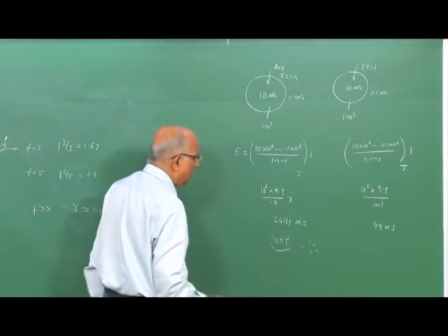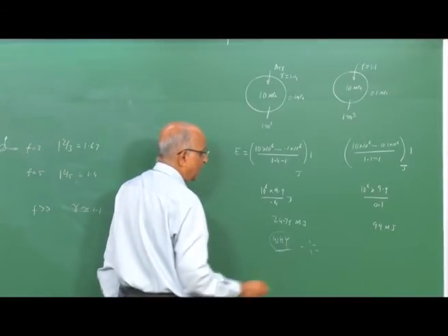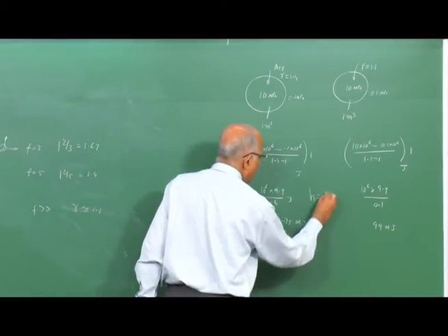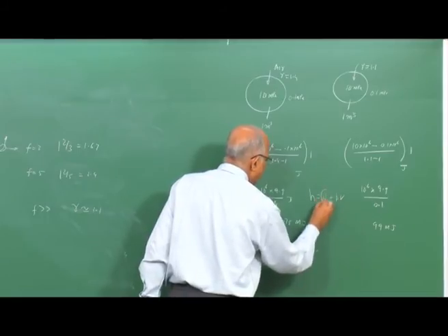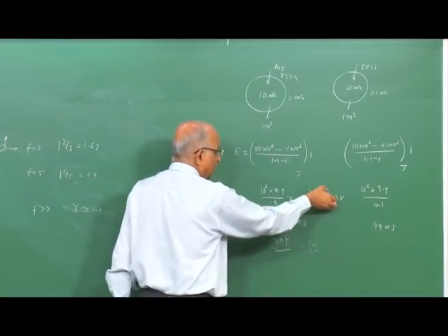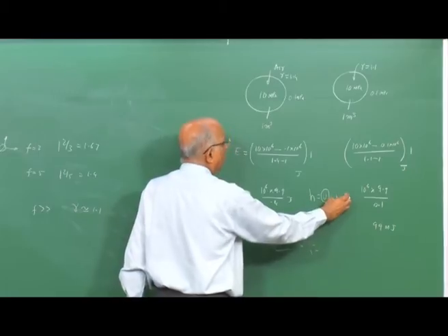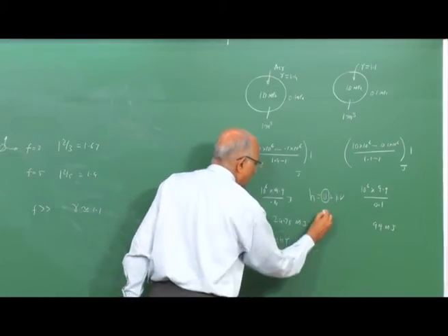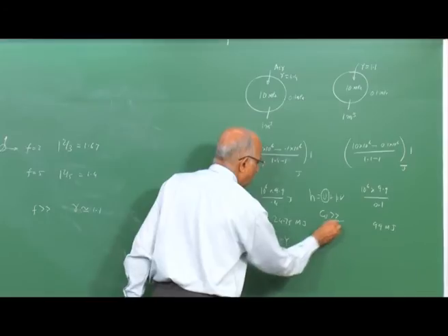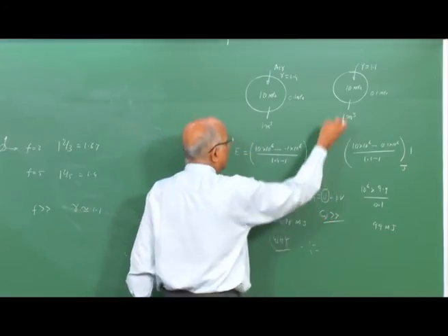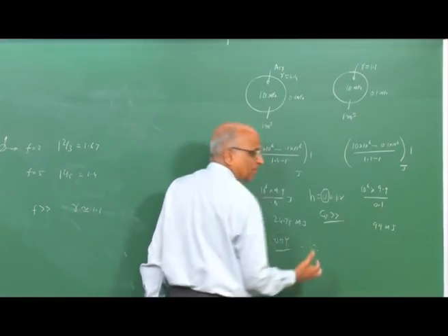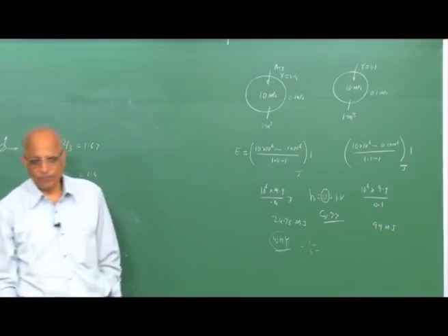But why should the internal energy change and not the enthalpy? H is equal to U plus PV. It is U which decides the internal structure which holds the energy. PV is just flow work which does not change substantially. Therefore, Cv tends to be high for the complex gases, and since it is high, it holds much more energy. This is the logical conclusion.